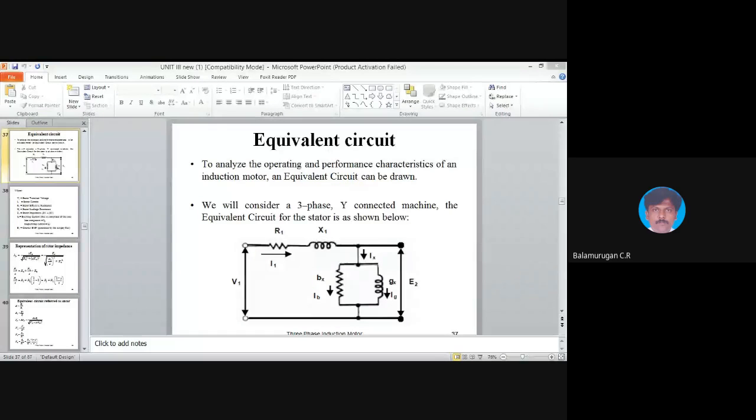And this is the reference from the rotor to the stator. So the EMF of the rotor referred to the stator, and these are all the parameters referred to the stator. You discussed this already; sir discussed it in the transformer itself. So what is the relationship? Here we have V2 by V1 equal to N2 by N1 equal to I1 by I2 equal to E2 by E1. Here you may use K or a value. This is the ratio between the rotor and stator as far as the induction motor is concerned.